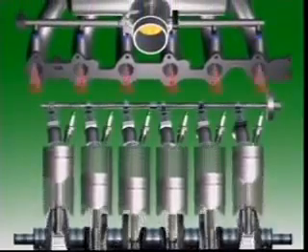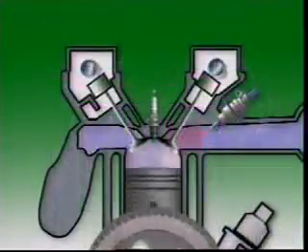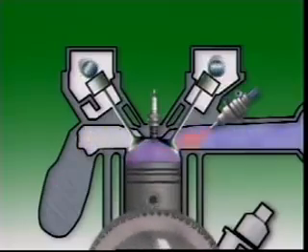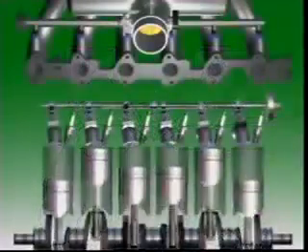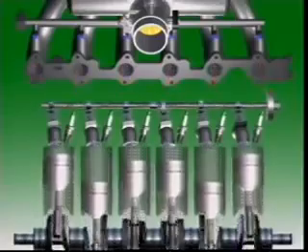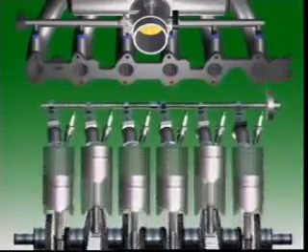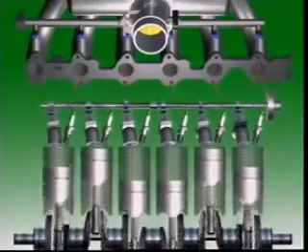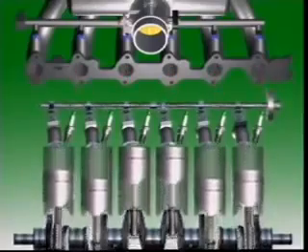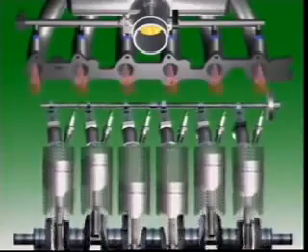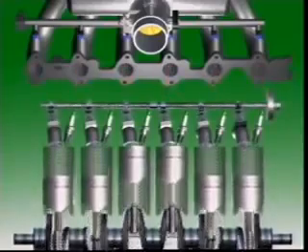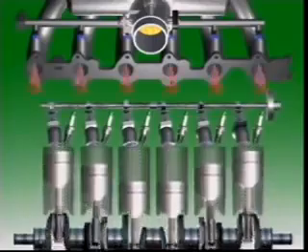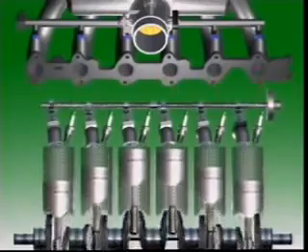Fuel sprays into each intake port where it stays until the inlet valve opens. During each engine cycle, the injectors open twice, and each time they deliver half the fuel needs of each cylinder. This happens regardless of the position of the intake valve. The injectors are triggered by the ignition system. So for a 6-cylinder engine, the control unit triggers the injectors on every 3rd ignition pulse.